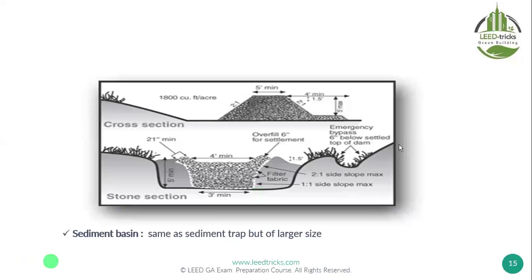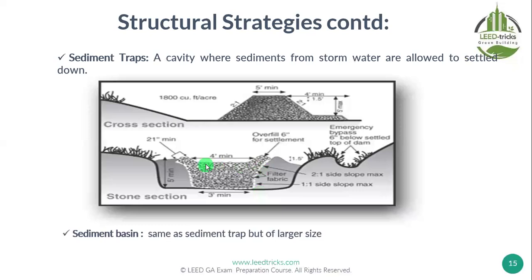For the sediment basin, we make some excavation and we put gravel here, so the water can easily infiltrate within the trap to the lower ground.